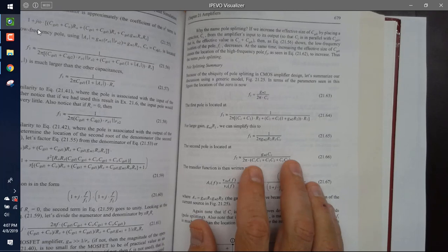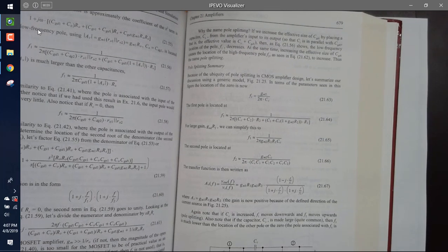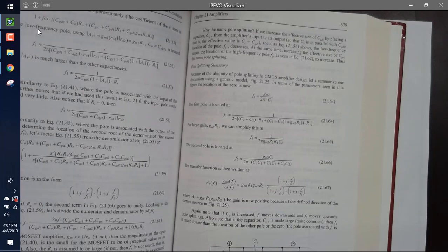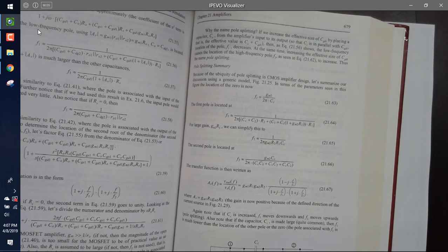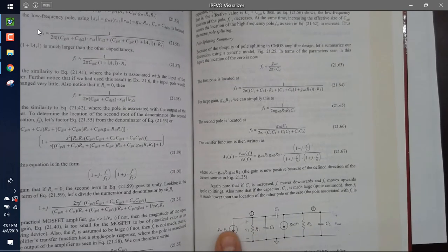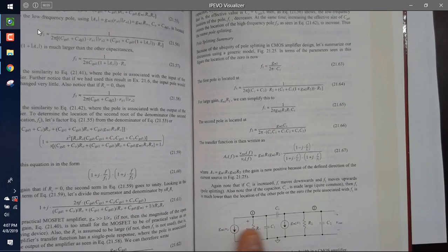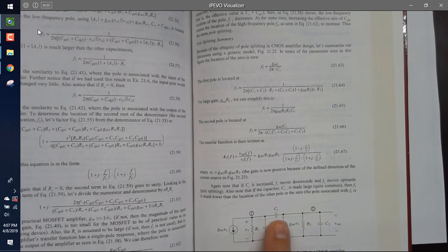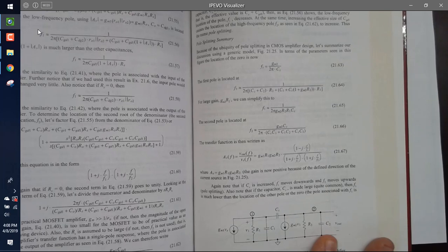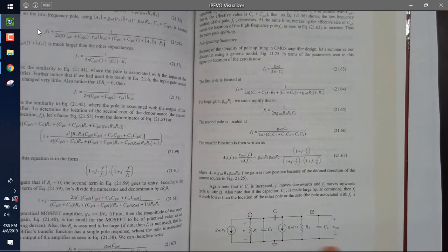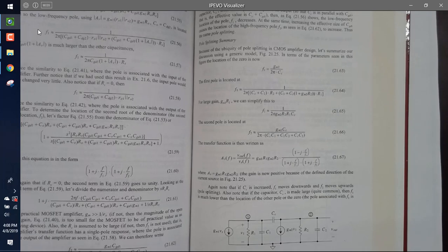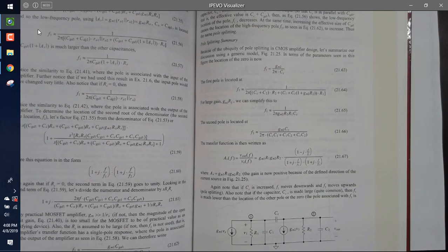Okay, so you see these equations? You don't derive those every single time. Rather, what you do is you use those equations. So when you do homework problem number 2, you're going to use those equations. And I want to go through, does everybody see that here I've got R1 and GM1 and S and all that? And you see I've got C1, CC, GM2, V1, R2, CC. I'm going to do homework 2 and then we're going to compare what I get to simulations, since you already did that, right?